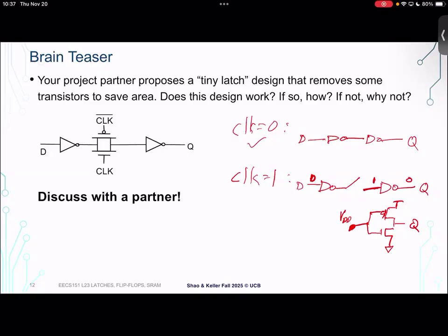There's leakage through the gate, and there's leakage backward through the transmission gate. So eventually, this charge sitting on this node will be in danger of leaking away. We can't guarantee that it won't. So yeah, I would be pretty nervous about using this in a modern design.